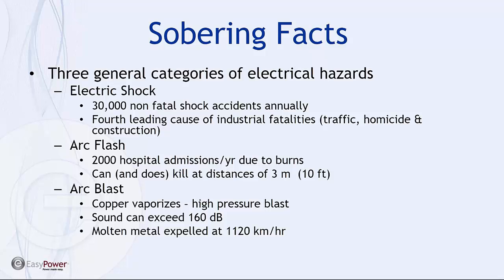So just to take a real quick look at this, the arc flash will produce a region of plasma where the high heat levels are generated, and that's the air where the electricity has actually ionized the air between the conductors. And the plasma ball in turn produces the larger fireball. With the same amount of energy, if the energy density is released in a shorter amount of time, it stands to reason the physical dimensions of the fireball and the plasma ball will be larger. And so the same energy released for a longer period of time may produce a significant fire hazard, but maybe with a smaller concussive force.